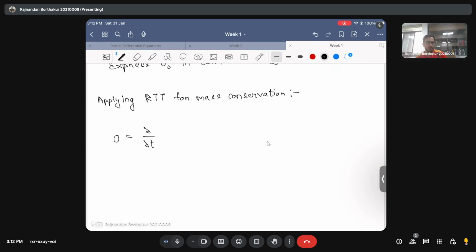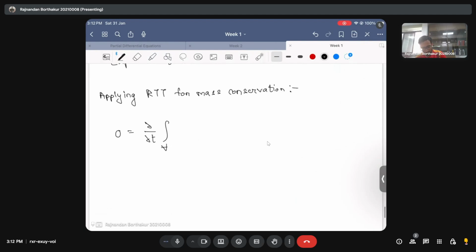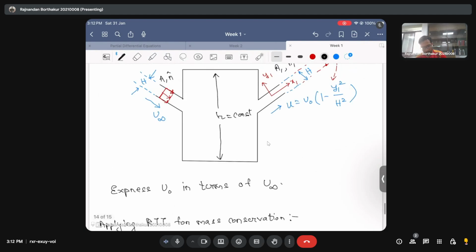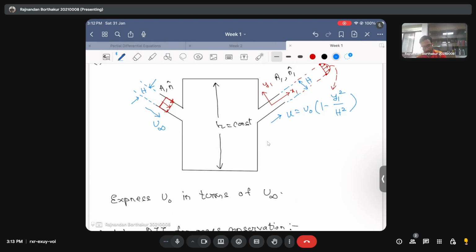The right hand side has the first term, which speaks about the rate of change of the property inside the control volume, which is del T of the integral over the entire control volume of rho dV, where I must now draw my control volume. So I'll choose my control volume as the one of the water that is encompassing the water level inside the tank.